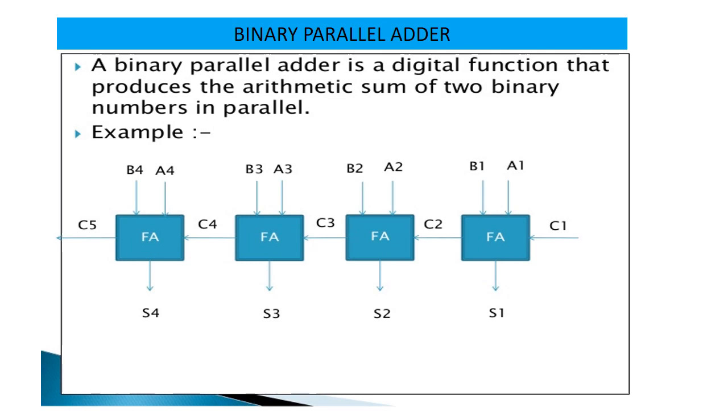The parallel adder in which the carry out of each full adder is the carry in to the next most significant adder is called a ripple carry adder. The greater the number of bits that a ripple carry adder must add, the greater the time required for it to perform a valid addition.